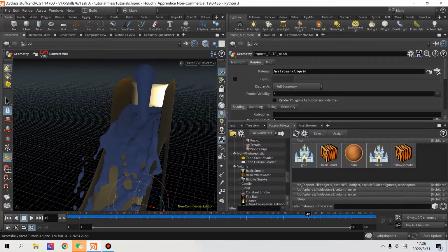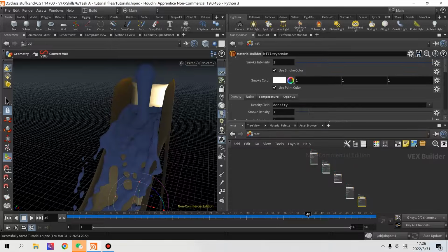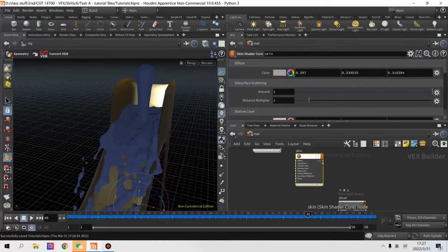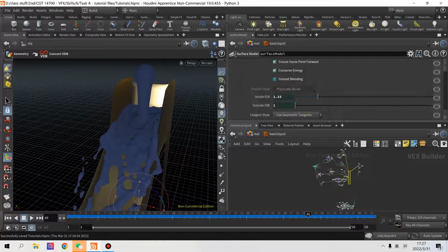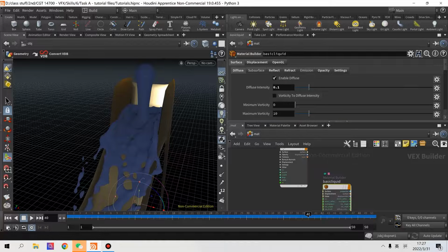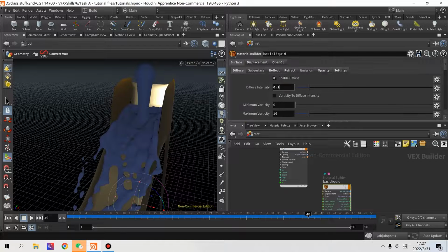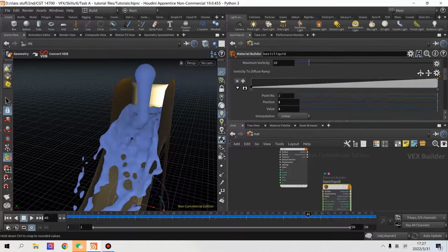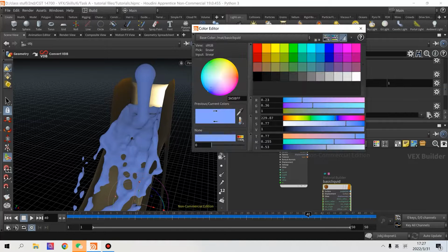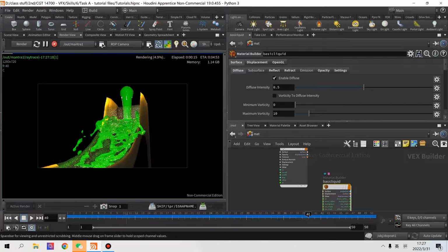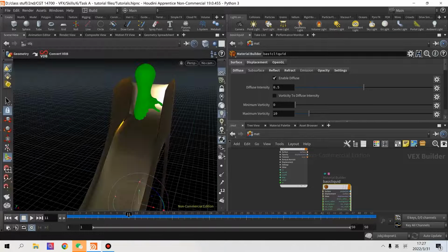As for the texture, we can always change that using the material palette. And we can go to the material interface, and we can see the basic liquid texture here. And we can change that by changing all of the parameters on that basic liquid interface. We can use all of the things here like diffuse. We can make it brighter. We can change its color because it represents some of the gooey effects, so I can change it to green. And we can see in render view that we can see all of the liquids and slime without any problems.